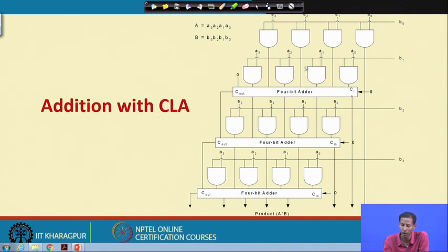At the very beginning it produces the 4 bit sum. Apart from that, the last sum comes out directly, then with that 3 and the carry out, it is again added with B2 A3, B2 A2, B2 A1, B2 A0. Then again the carry bit and the last sum come out from this, and finally I get the product like this.